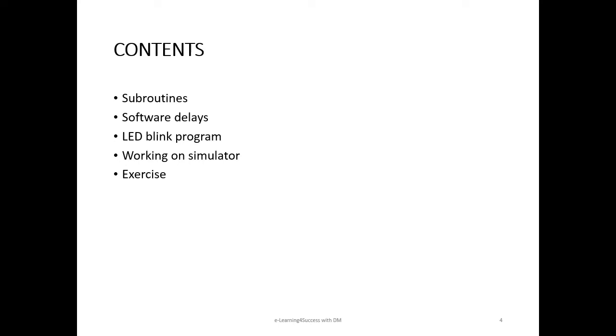Next we will interface LEDs to 8051 microcontroller and write an assembly language program to blink them at regular intervals. For this we will be using the delay subroutines that we have written. After this we will copy this program to the 8051 simulator and run it to see its working. This lecture closes with an exercise question as an assignment.